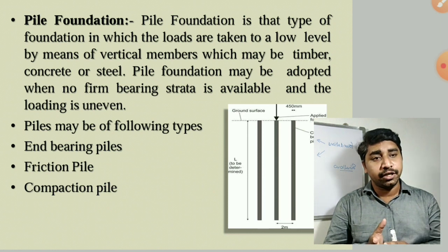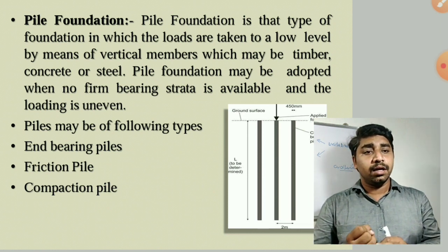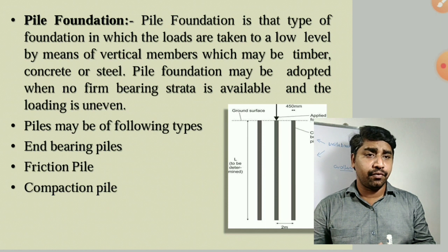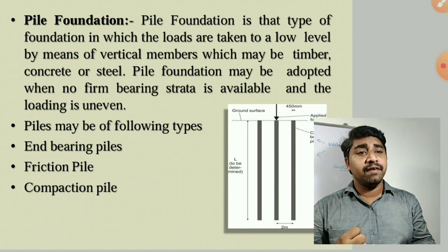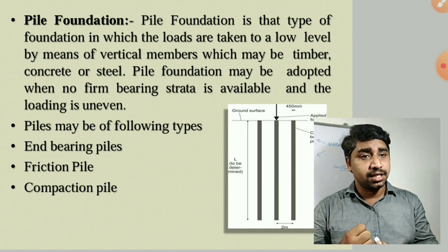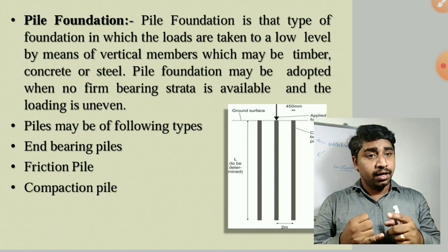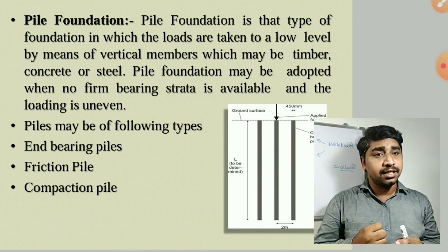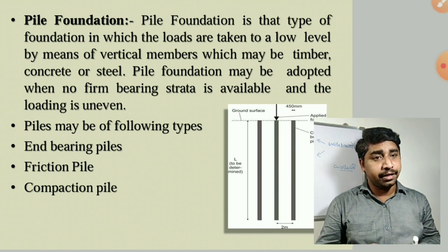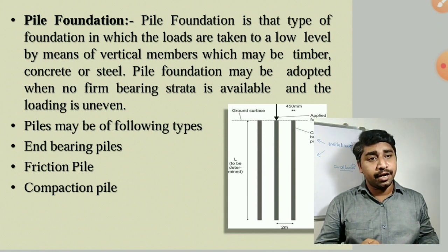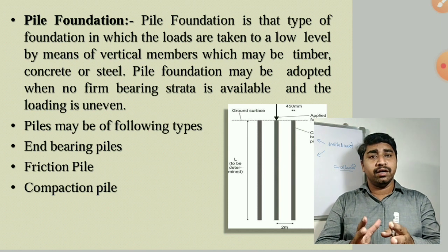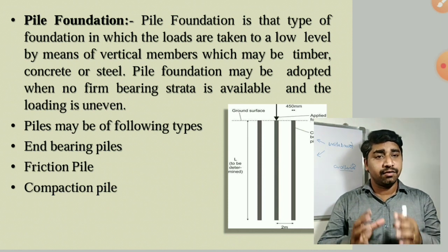So where are we going to use these deep foundations? Firstly, if the hard strata is available at a greater depth, if the depth of availability of the hard strata is somewhere 30 meters, 40 meters, 50 meters or 100 meters, then we'll be going for deep foundations instead of shallow foundations.